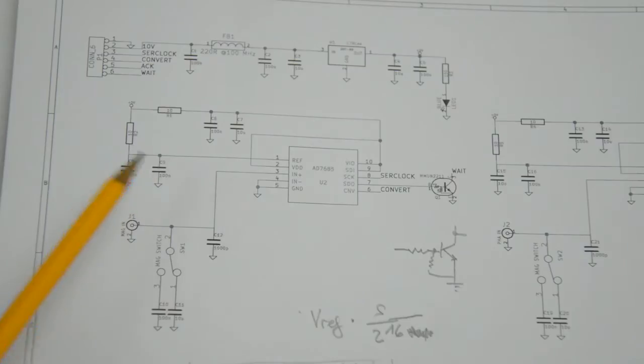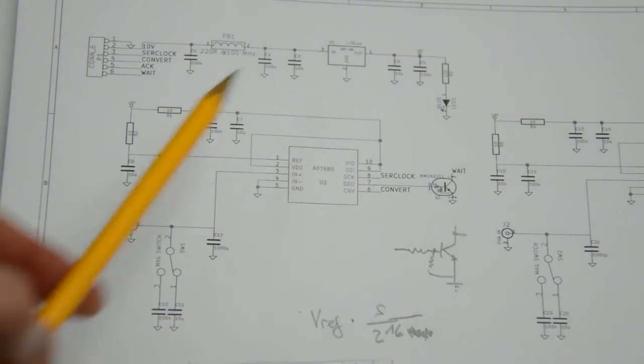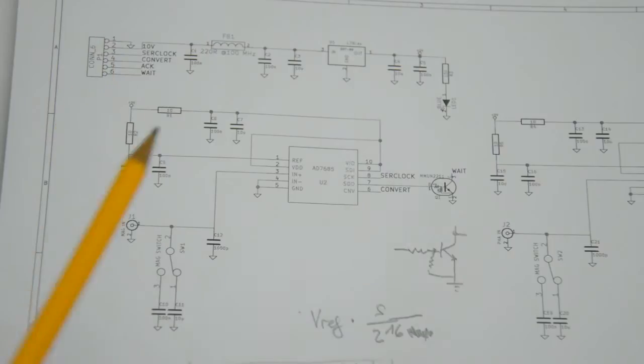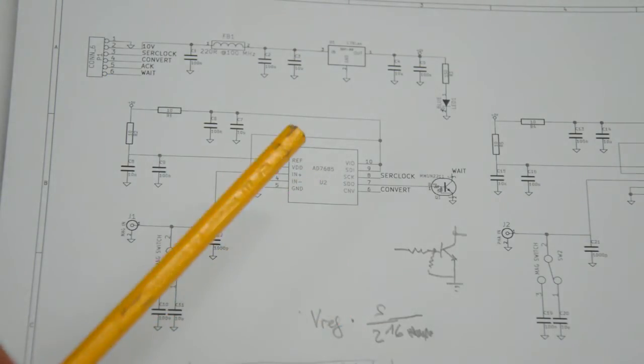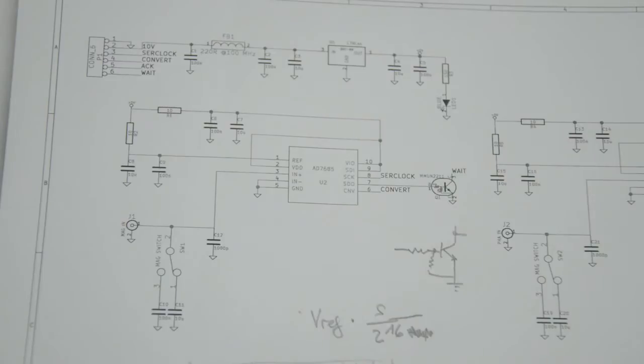But still, the reference is connected to the regulator here. That is a box standard regulator, and the tolerance on this is, I think, plus or minus 250 millivolts. So even though you've got some good resolution here, you have pretty bad accuracy, because you have no idea where your regulator is actually regulating. In fact, as a minor detail, even though the tolerance on the regulator is pretty high, this doesn't mean that it might jump all over the place.